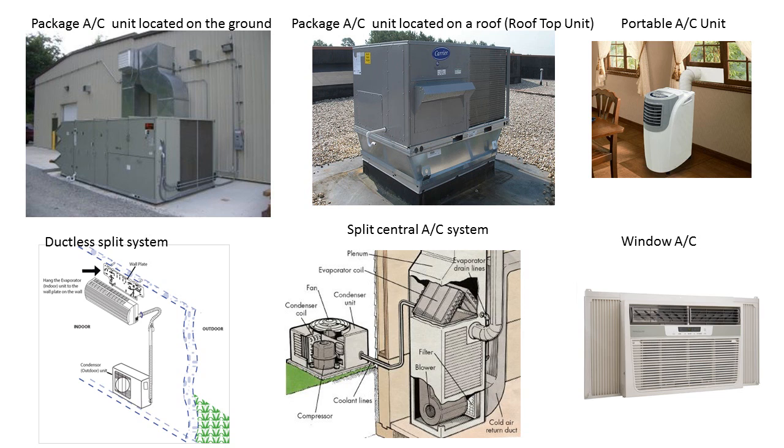It is designed so the condensing unit, which contains both the condenser and the compressor, is outside, and the evaporator is mounted on a wall in the conditioned space. Since the components are separate, an HVAC serviceman will need to connect the piping and electrical work between the two. These units do not use ductwork. They only cool the room they are located in.